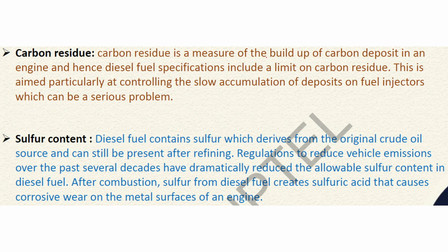Then the carbon residue is a measure of the buildup of carbon deposits in an engine, and hence diesel fuel specifications include a limit on carbon residue. As I told, during the combustion of a diesel fuel, the diesel fuel may leave some amount of carbon residue. There should be no buildup of carbon residue on the engine, otherwise the performance of the engine will be restricted.